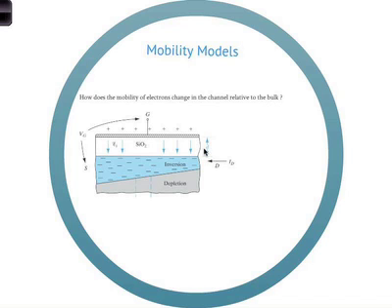Of course, the electric field is orthogonal to the flow of the electrons, so this is not the typical saturation we talk about. Earlier we had a plot where velocity is a function of electric field, and it was a straight line, and at some point it's saturated, right? And the slope of this line was mu, mobility.